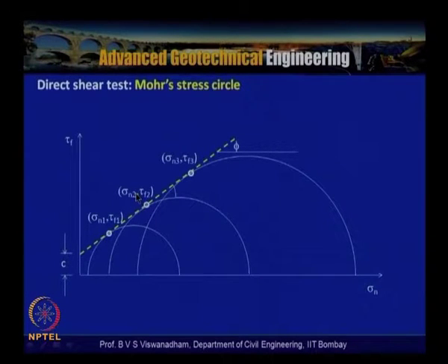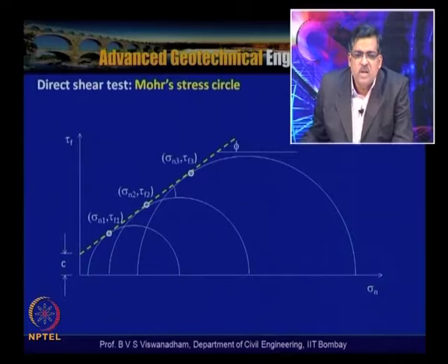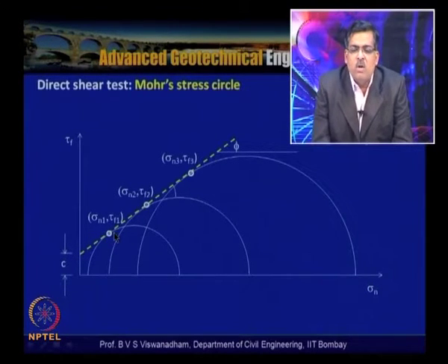Further, there is a way where we can construct the Mohr circles, because in this case we can construct the Mohr Coulomb failure envelope, and we know this particular point. The Mohr Coulomb hypothesis states that when the Mohr circle is in contact with the failure envelope, that is the point where the failure shear stress tau is achieved at a particular normal stress.